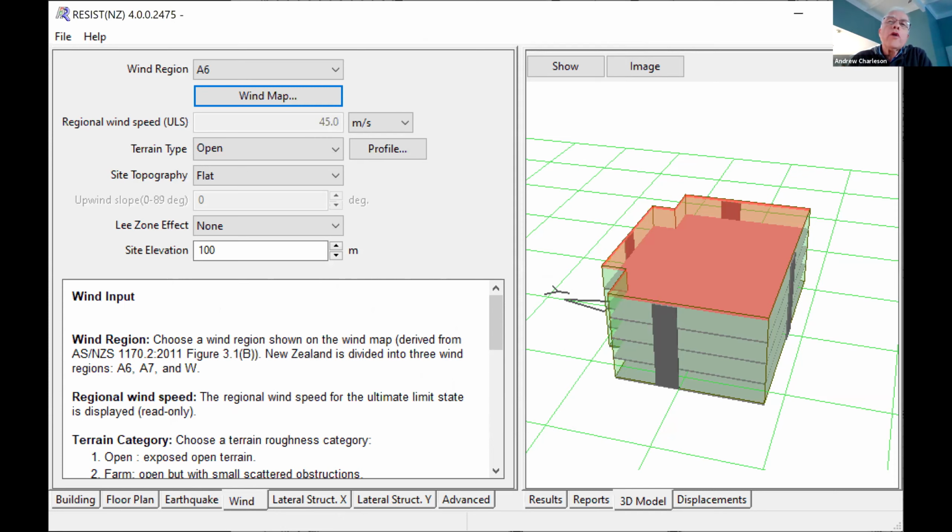In Indonesia, you have quite low wind speeds. And also in Indonesia, your earthquake loads are always a lot more critical than wind loads. The only exception is if you're designing a timber building. And so usually you can neglect the wind load acting on your building because the earthquake forces will be far, far greater. So we won't worry about wind load.